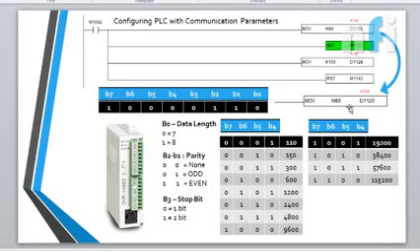So it's H86. Now D1120 is a specialized data register inside a PLC which defines its communication parameters. That data register is the default for this PLC, Delta DVP14SS. It can be different for different PLCs, but it is there. So if you are doing Modbus in this PLC, surely you can do that in other PLCs too. You just need to understand the basics. The basics are that we have to configure the devices with the same communication parameters. Alright, so now let's see what will happen if I put H86, which is 134 in decimal.